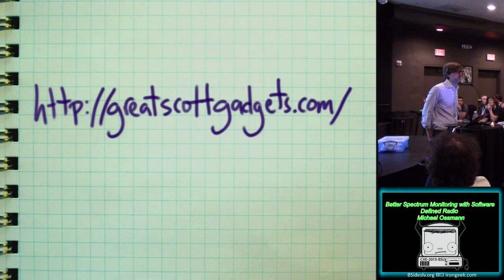I would say it really depends a lot on the very particulars of your application. There are some antenna designs that are very wide band, like for that measurement that I took in a hotel room. I would have been much better off using a discone than I would using a telescopic antenna. But the difference is a discone doesn't fit in my backpack. So that's not what I had at the time.